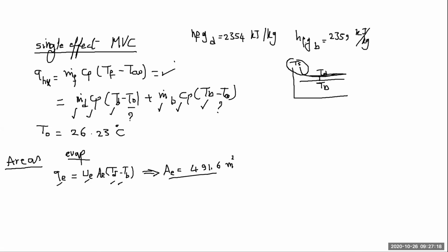Yes. Fine. Then, if we are going to look at the other two heat exchangers, then the distillate heat exchanger, for example, we have T distillate is going to cool down to T naught in order to preheat part of the feed from T cooling water to T feed. So we can calculate the log mean temperature difference for the distillate preheater.